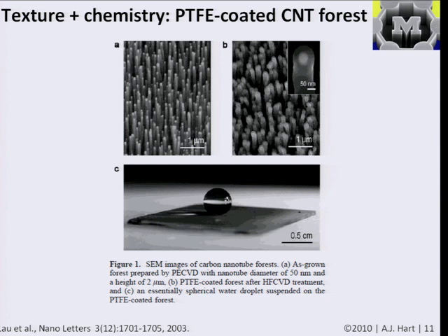So it's favorable for the liquid to stay up above, on top, and also the low surface energy of the Teflon relative to the surface energy of water is going to promote the surface to want to repel the droplet, and it turns out that you get a surface that is extremely hydrophobic. And this was interesting because it combined this effect of texture and the effect of the chemistry of the coating, the low surface energy of the molecule itself, and also at that time was one of the most hydrophobic synthetic surfaces observed. Typically, people say something is hydrophobic when the contact angle is greater than 90, but in this case, it was essentially spherical. It was almost a perfectly non-wetting surface.